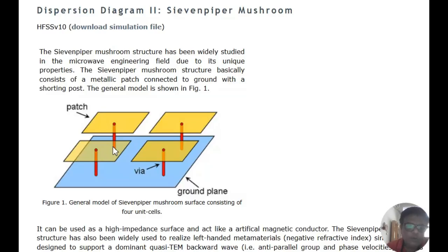If you plot the equivalent circuit diagram of this structure, you will find that a conducting surface represents an inductor, and this gap represents the capacitance part. The next conducting structure again represents the inductive part, and both inductors are in series. So the equivalent diagram is an inductor, then a capacitor, then an inductor. The capacitor is sandwiched between 2 inductors, and there is a ground plane.